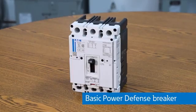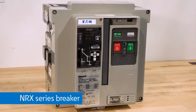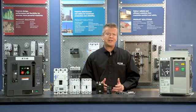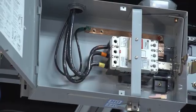Molded case breakers and insulated case breakers like these Power Defense breakers and NRX breakers are available in much larger size ranges up to 1,000 volts and more than 2,000 amps. These breakers can interrupt higher fault currents depending on the model, even up to 200,000 amps. MCCBs are used in many types of applications in standalone enclosures, panel boards, switchboards, motor control centers, and busway.